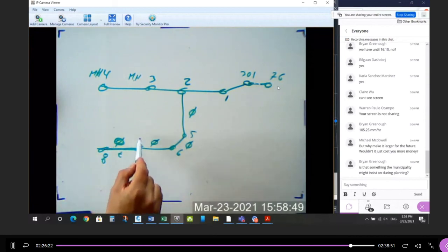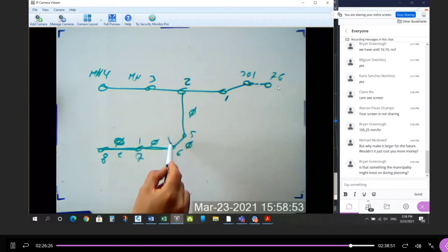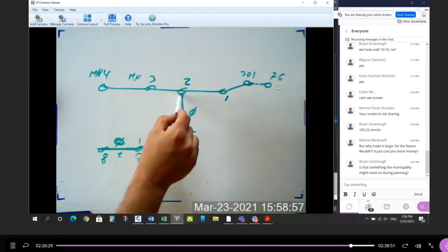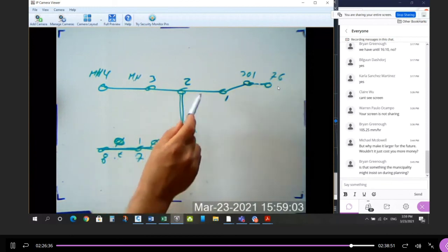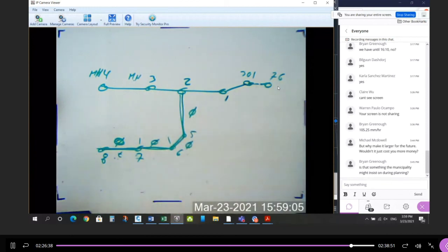So you want to set the time to this point here before you design this pipe, and set the time to here before you design this one. So always design from the top of the system, the dead end at the top, in the direction of flow, always toward the bottom. That way you're not going to upset the time sequence.